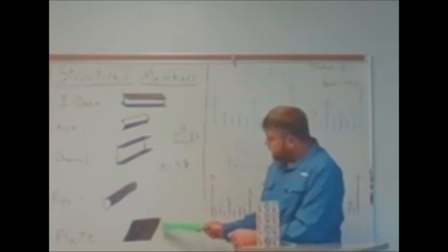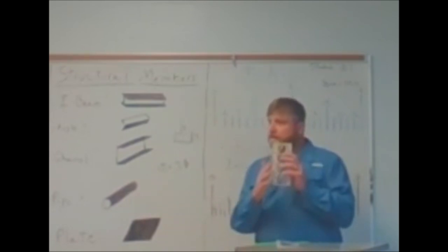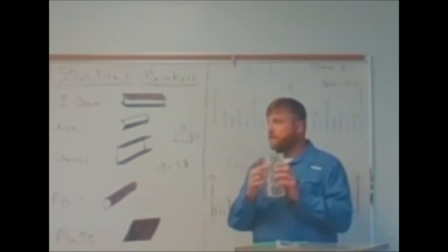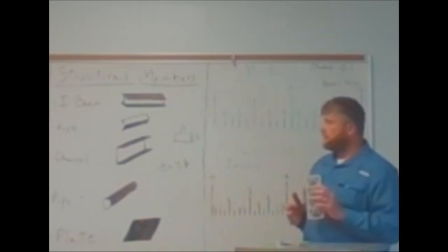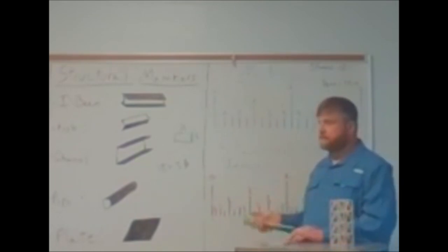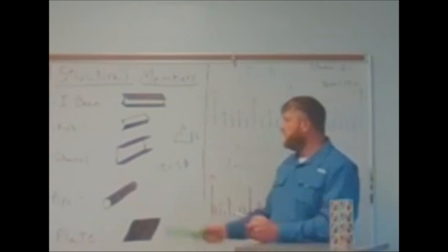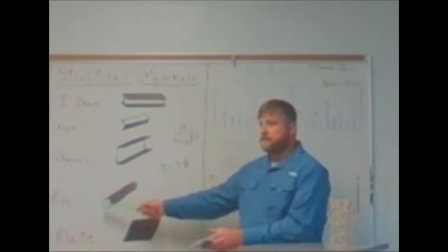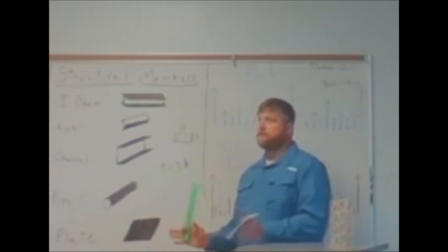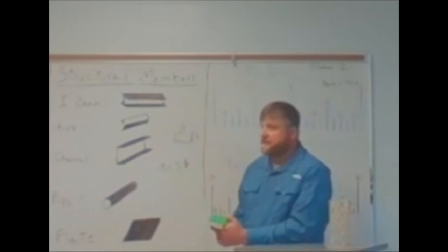Now, pipe is not, so all those, you can use plate because that surface is flat. All of those flat surfaces come together at that point. So you can use plate as a splice plate, right? You can weld a flat surface to a flat surface, right? Weld it, bolt it together, however you want to do it. You bring pipe in and you weld plate to the end of it, and then you bolt it or attach it to a flat surface structure. Okay. That's not very economical.